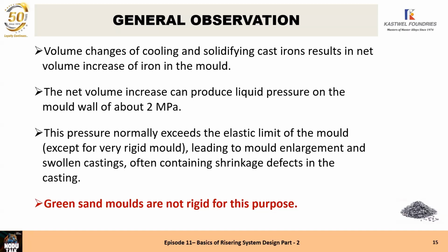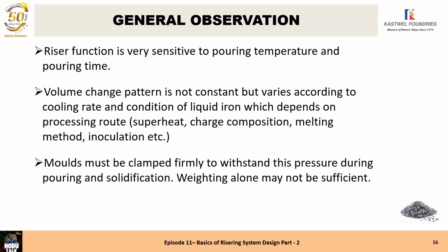The pressure is normally more than the elastic limit of the mold material, and this causes mold enlargement or oversized casting, and these castings mostly contain some defects inside, shrinkage defects inside. Now, riser functioning is very sensitive to pouring temperature and pouring time.